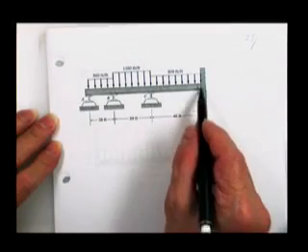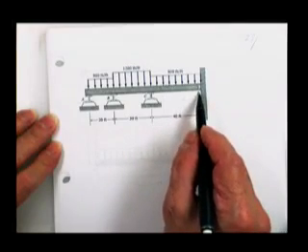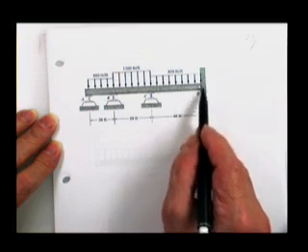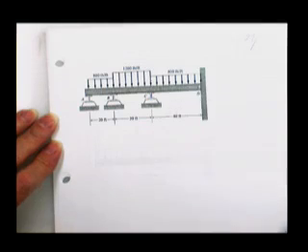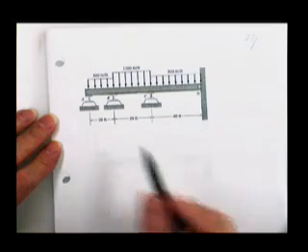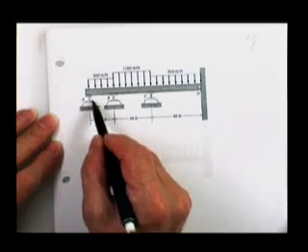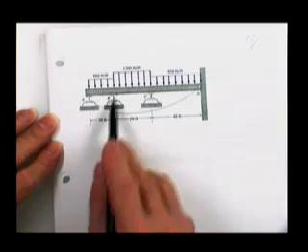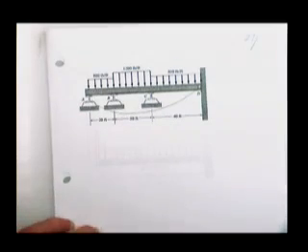Cantilever beam. It's just got a little clip angle shown. We already discussed that they're not any good for moment. They're great in shear. They hold tons of load in shear. But when the beam wants to roll 1/3 of a degree, there's just no way you can stop it. The bolts won't even probably hit the side of the angle by that rotation. Make it a cantilever beam. Get rid of these 2 unknowns, or those 2 deflections.